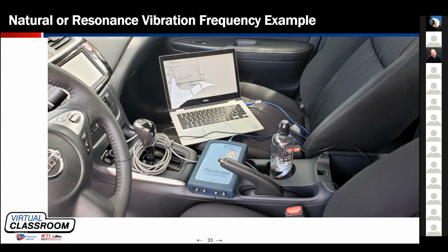And then out of the speakers of the car, I can run a sound generator rather than the stereo, but an adjustable sound generator. And here's what I do. I take my sound generator and I slowly start applying more and more frequency to it. As I apply frequency, I just sit there in the shop and keep going louder, louder, faster, faster, until I hit the natural frequency of the component that the rattling piece is stuck to.